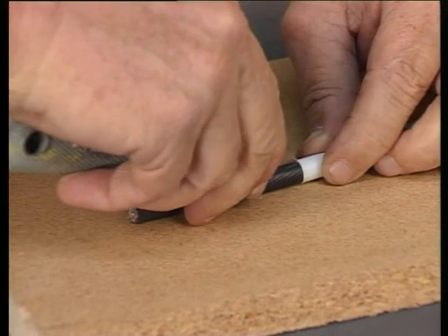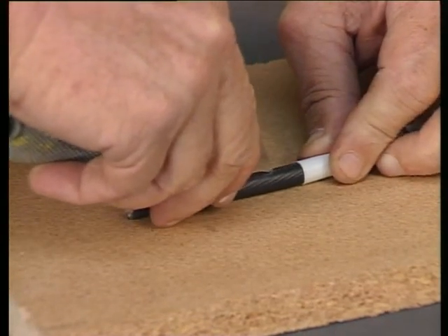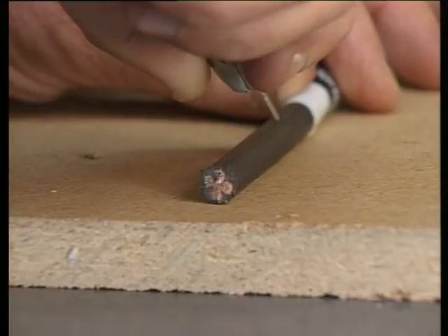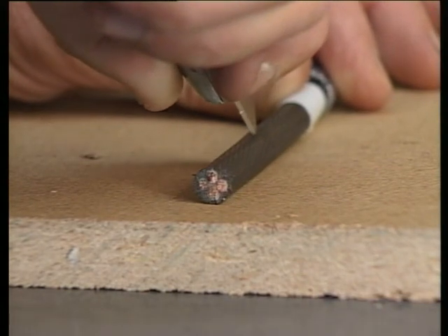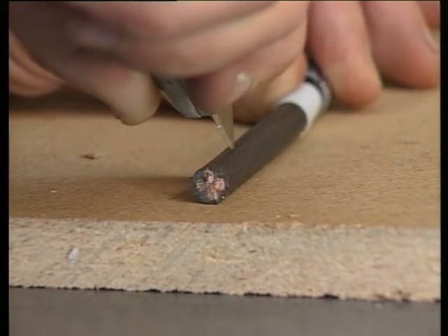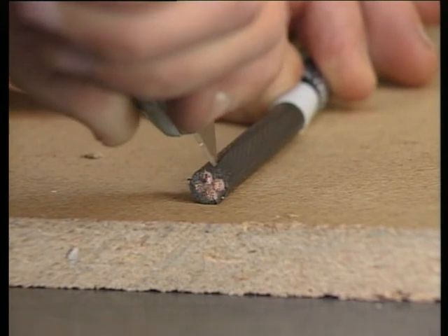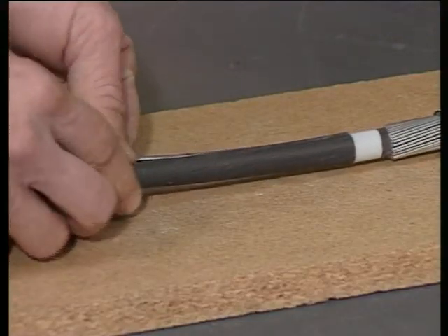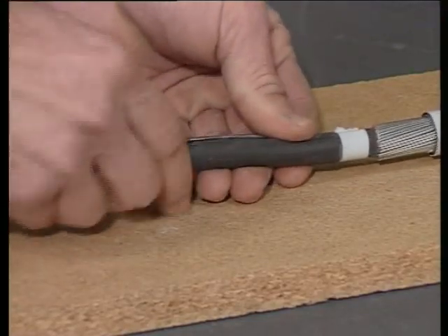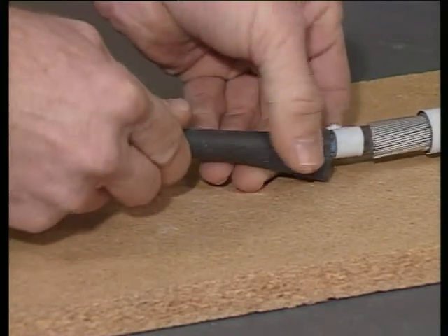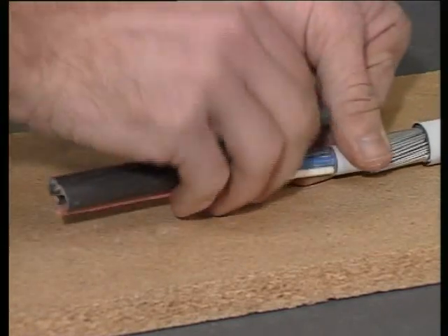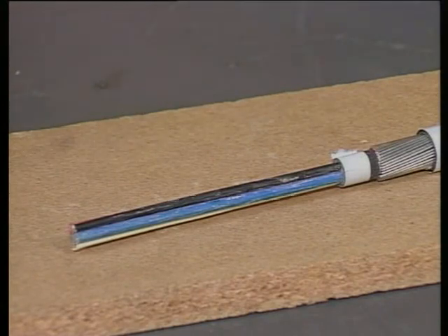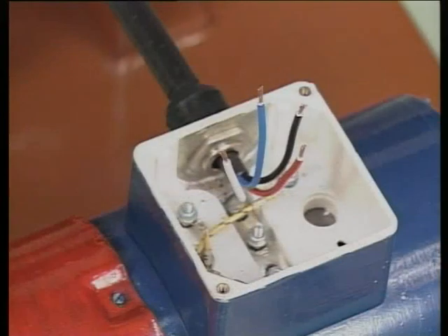A longitudinal cut is next made. This cut, too, must be made carefully to avoid cutting into the conductors. The cut is not made all the way through the bedding so as not to damage the conductors beneath. Once the cut has been made, the bedding can be peeled off to expose the conductor cores. A properly prepared cable end appears neatly finished and will greatly assist the safety and efficiency of the cable installation